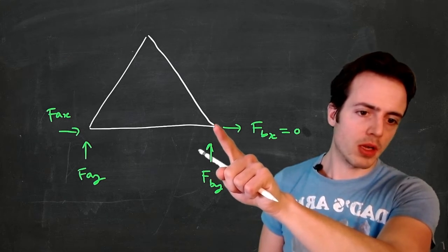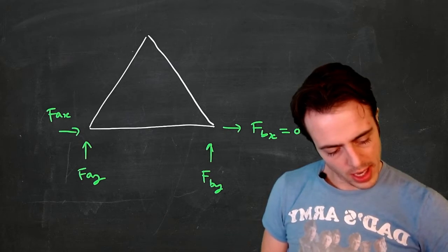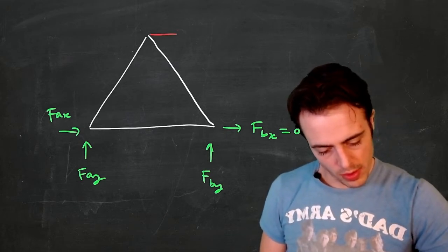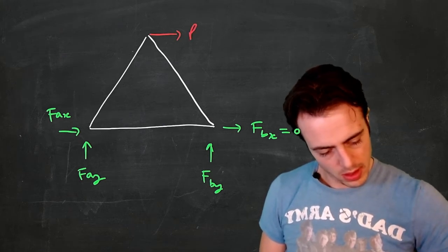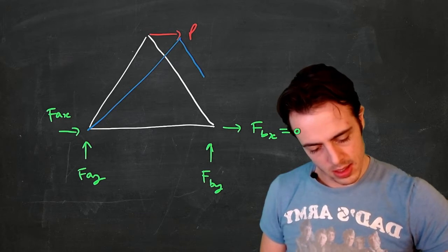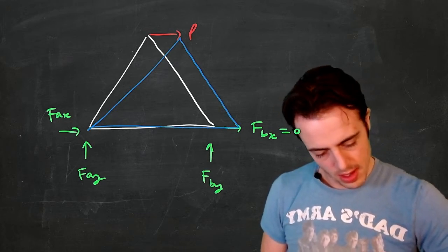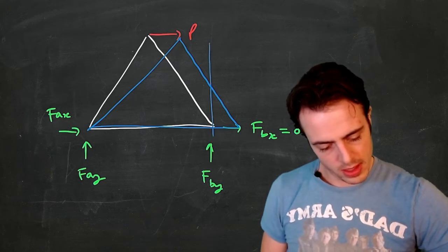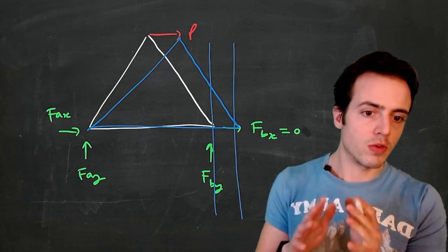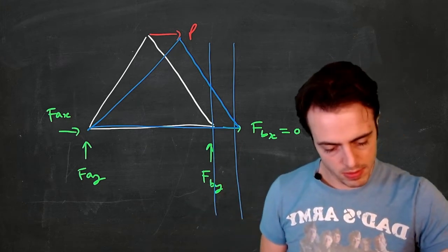So if we apply our loading and set this equal to 0, the structure is going to move somewhat. So let's say the structure moves in this big exaggerated loading to something like this. This distance that we would have determined is defined in the same direction as the redundant reaction.